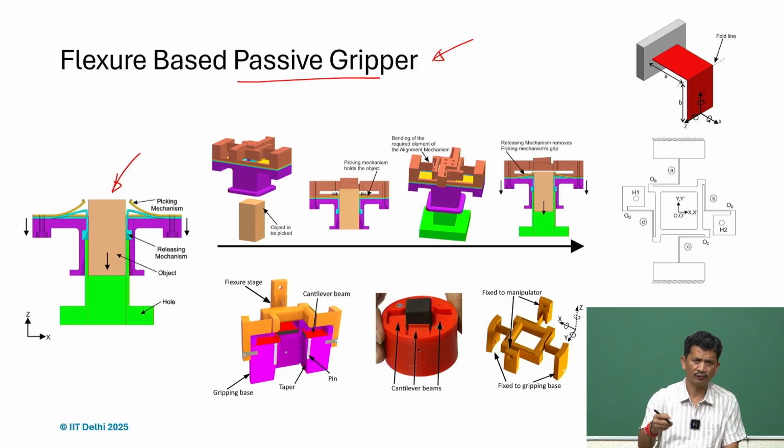So for instance, if you want to pick up some part and precisely put in a certain kind of tube, we can use that compliance. So for instance, in this case, the constraint is only in the pushing direction, we want to place it, but we want that because of the interaction between the hole and the object, this should comply and it should find a way on its own, and therefore we design based on that principle.